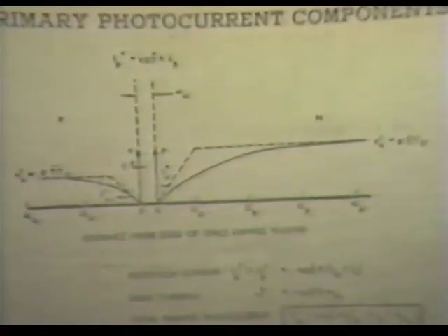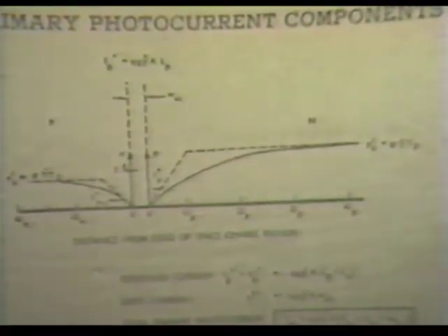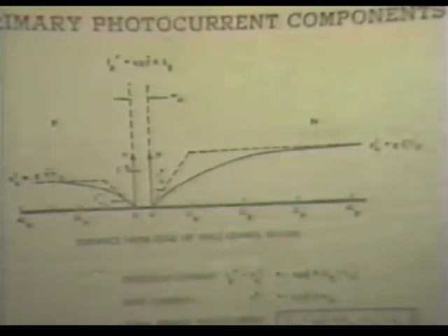The ionizing radiation coming in a pulse creates a pulse of photocurrent which for a short period of time upsets your logic and turns your device on, but as soon as your circuit potentials restore themselves and sweep those carriers out, you'll go back to some stable state of your device, maybe not the initial one. So the upset from dose rate is a transient phenomenon.